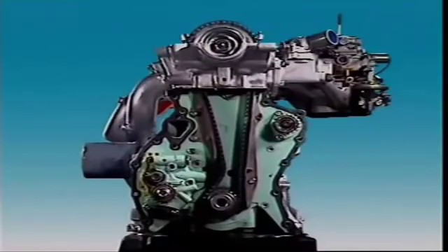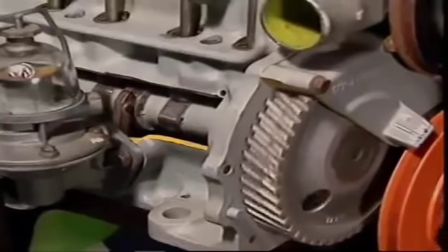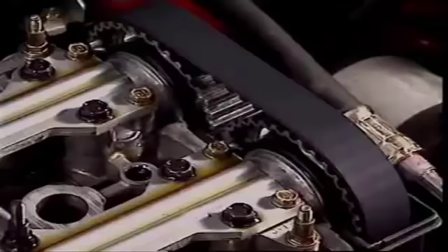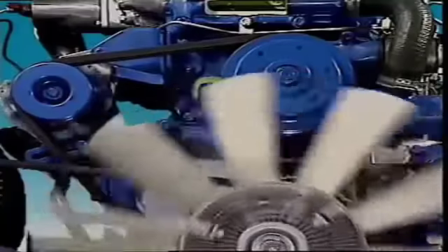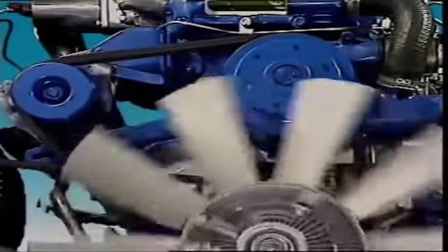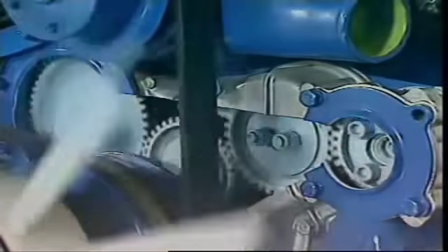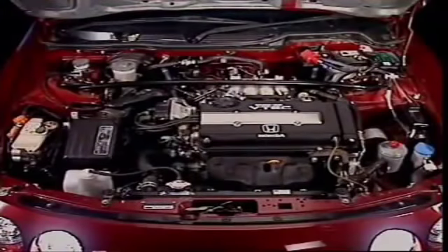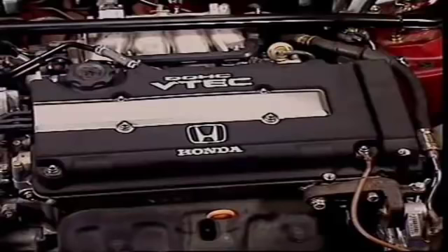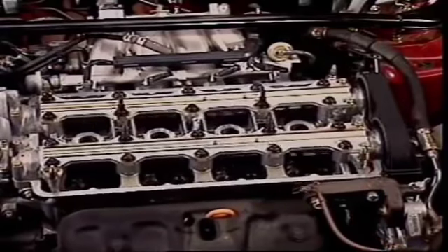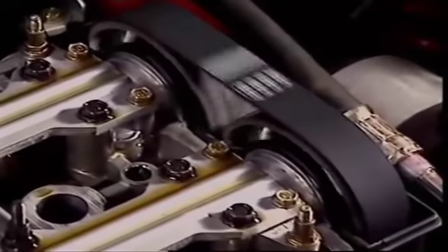The camshaft must always be synchronized to run in time with the crankshaft. This can be done by gears, chains, or toothed timing belts. Gear drives are most common in engines with the camshaft in the cylinder block, and in heavy-duty diesels. Timing belts and chains are used on overhead camshaft engines because the camshaft is further from the crankshaft.